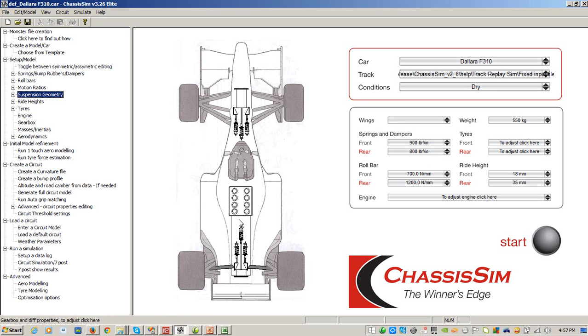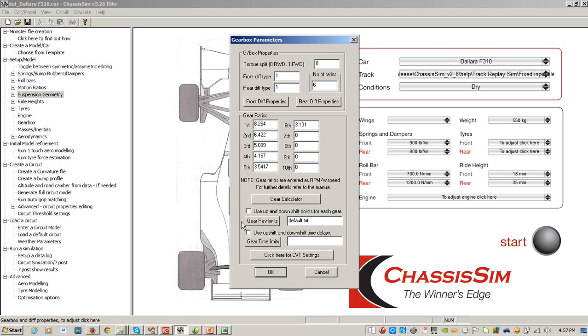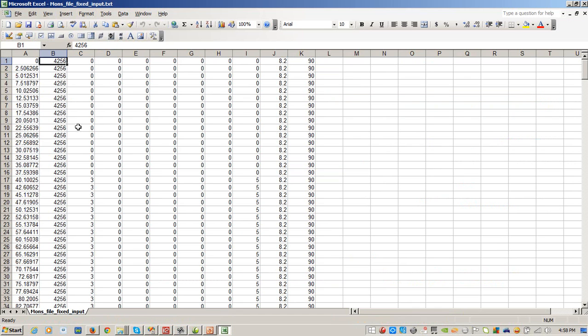I knew my speed was 90 km/h, so I clicked on the bell housing and looked at a couple of the gear ratios. Second is a torque ratio of 6.4, third is 5.09. I took the 90 kilometers per hour, converted that into the rotational velocity, divided that by the gear ratio, and from that I was able to deduce the RPM. That formed that entry here.